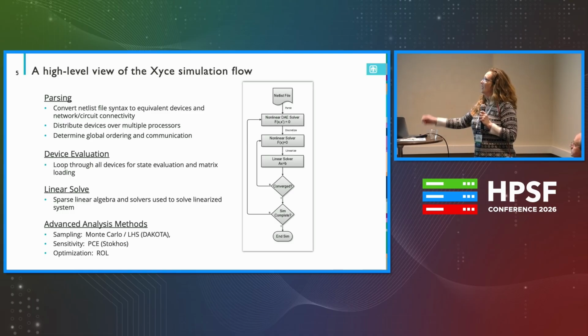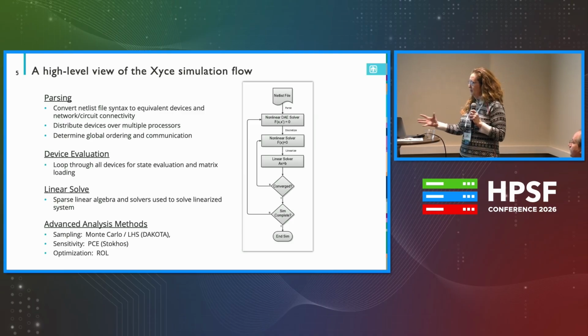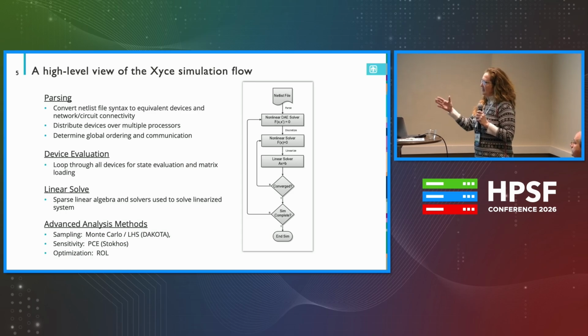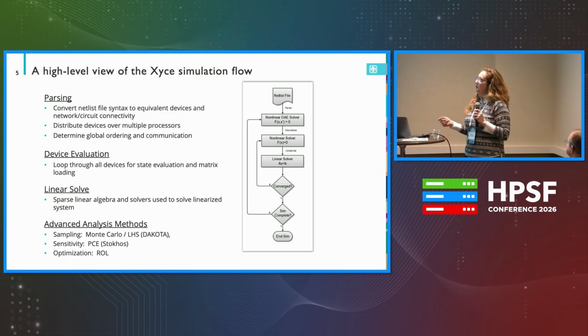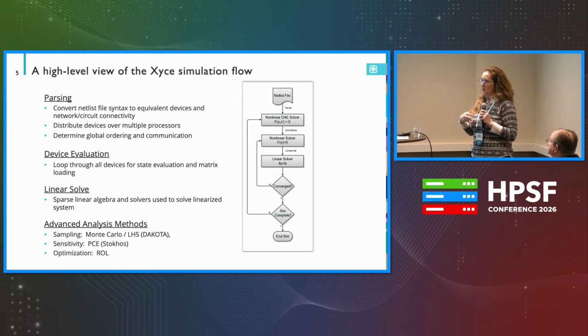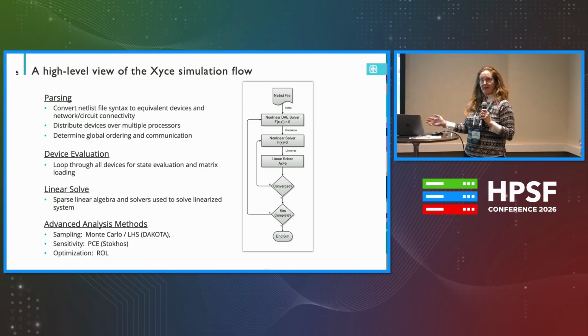For those who have familiarity with a PDE type of simulator, there are various stages in which you're going to mesh, break it up over processors, and do these pre-work steps in order to simulate anything that comes from the PDE space. For circuits, you basically get a netlist. You get a file, an input deck, and you don't know how big it is or how small it is. It's just handed to the binary, and you have to figure it out on the fly. So that makes it fun and a little bit challenging.